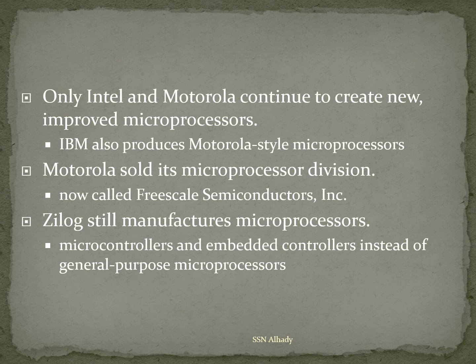So what is a microprocessor and what is a microcontroller? The 8051, the one that you used in the previous lab, is a microcontroller. It means it has a whole system built in a single chip. It has memory, it has I/O ports, it has a timer, all built in. A microprocessor is only the microprocessor. In order to develop a system, you require memory, I/O ports, and so on.